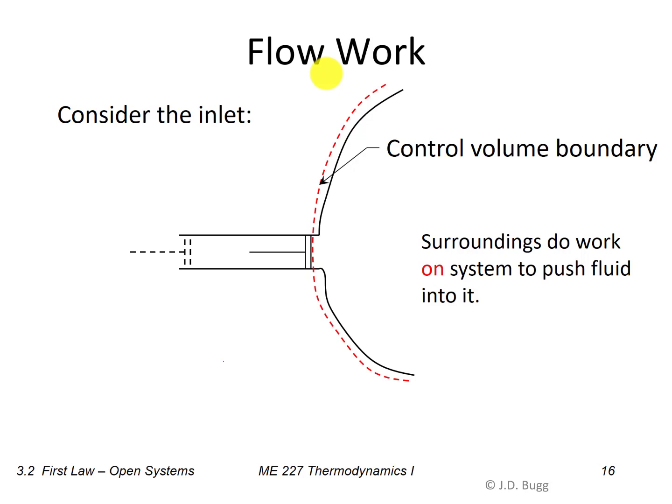In these open system analyses, we absolutely have to account for the flow work. In many cases, it's the most important energy transfer going on. So we need to figure it out. We can't just neglect it and hope that it's not very important. It certainly is. So to quantify this flow work, we need to think about what properties of the fluid in that inlet pipe are going to contribute to that work calculation.